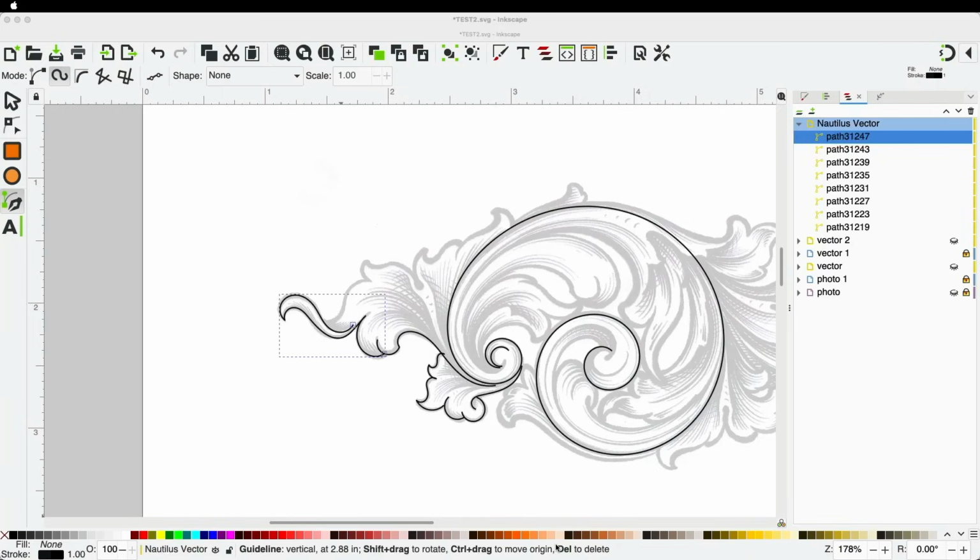Then I would scan that drawing back in and shrink it back down, so when transferring it to the steel I had a very fine line to follow. I just prefer engraving against a fine line. Most of my designs are fairly small and intricate. Having a thick line, I end up getting bends and kinks in my scrolls because it's difficult to follow the line accurately.